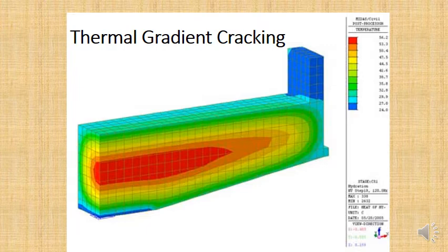Now, a dam is a very big body of concrete, isn't it? So in the middle of the dam, that concrete is going to be a long way from the surface. So it has no outlet for the concrete to cool and for the heat of hydration to escape. But the surface does, of course. So that creates a big thermal gradient crack in the concrete. You do not want cracks in the concrete of a dam because dams are meant to be waterproof. They're meant to stop water getting through and going downstream.